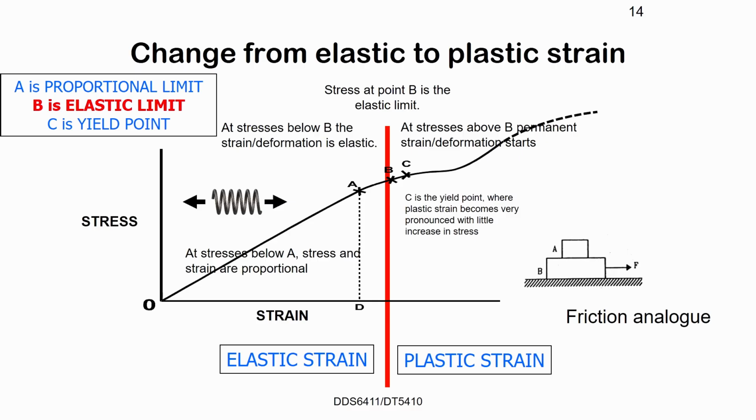It's a bit subtle, I know that, because I went through the same thing. I always thought nonlinearity means inelasticity, but it's not the case. So you can have nonlinear but still elastic behavior. But if you go beyond point B, you're going to have permanent plastic deformation. When you remove the load, your curve is not going back to the origin.